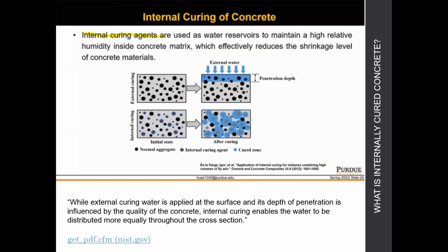Sure. I would say since about 2013, our firm has been involved in commercial internal curing. I don't know if that's necessarily the longest with these newer types of internal curing measures in the world, but we had to have been pretty close to about the first. And like Kristina described earlier, it's about a way of delivering water more evenly so that the hydration, the curing, is optimized.